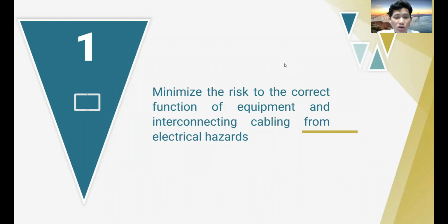The sensitivity of electronic equipment is in large part determined by the accompanying cable system. If there is no separation of different types of cable in separate cableways, or a minimum distance between high and low current cables, electromagnetic coupling is at its maximum. Under this condition, electronic equipment is sensitive to EMC disturbance flowing in the affected cable.